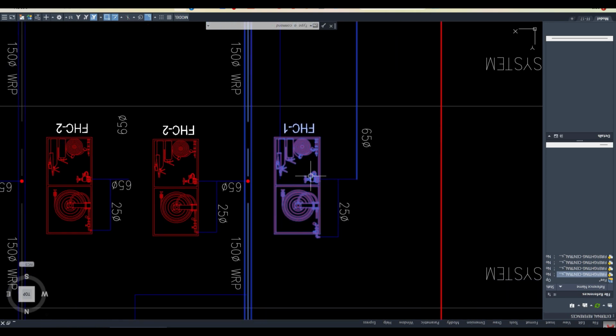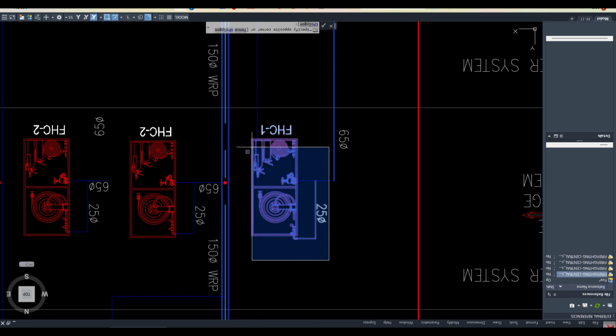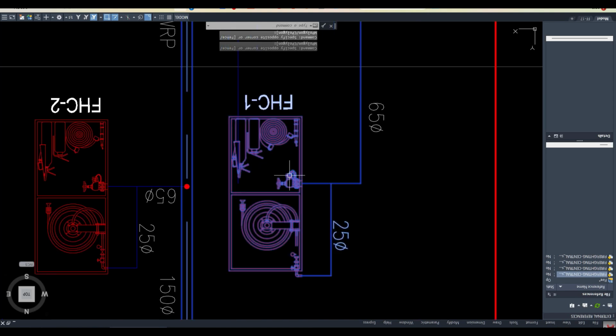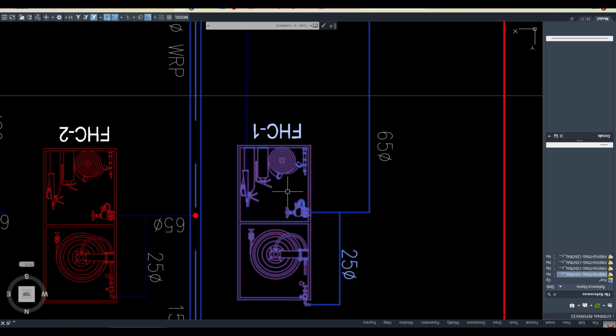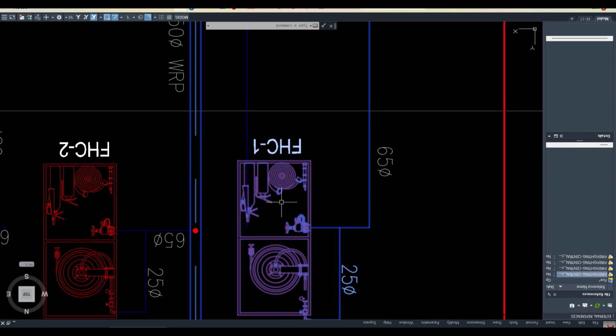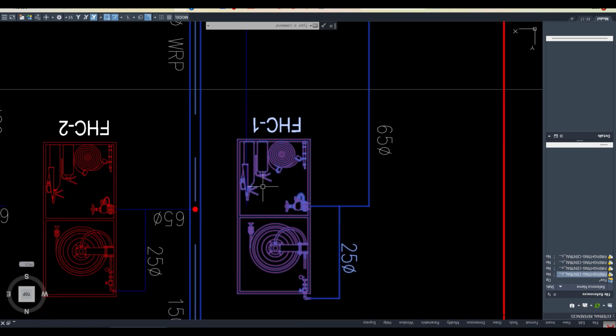Now, one question you should ask technically, which none of you asked me: here you see this requires 6.9 bar pressure, which is higher pressure, and this requires 4.5 bar, which is lower pressure. Why 4.5? So that a normal person can handle it. Why is this 6.9? So that it can reach the longer space and suppress the fire more quickly. And this is to be operated by firemen, so they can handle it. Not easily, but they can handle it at least.